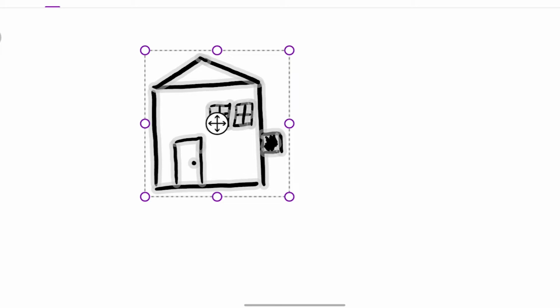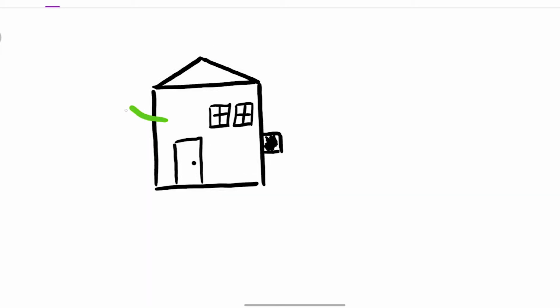We have the house that's losing 55,000 kilojoules every hour, right? And we're saying that if we want to keep this house at its cozy 25 degrees Celsius, then we need to put back the same amount of energy.